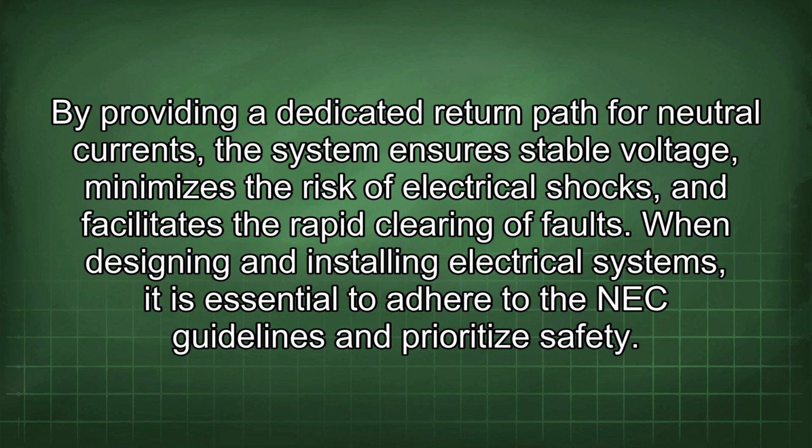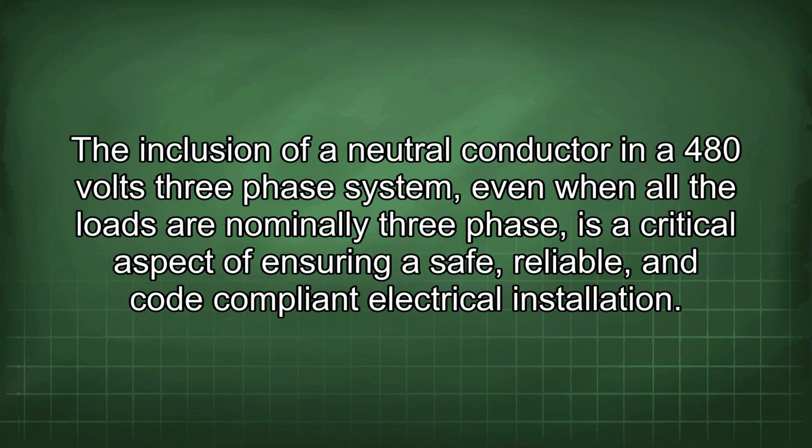When designing and installing electrical systems, it is essential to adhere to the NEC guidelines and prioritize safety. The inclusion of a neutral conductor in a 480 volt three-phase system, even when all the loads are nominally three-phase, is a critical aspect of ensuring a safe, reliable, and code-compliant electrical installation.